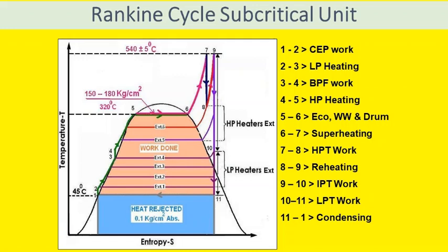Post expansion of the steam in the HP turbine, it is again taken for resuperheating or reheating. So 8 to 9 represents resuperheating or reheating in the boiler, though you see the pressure of reheating is less than the pressure of superheating.